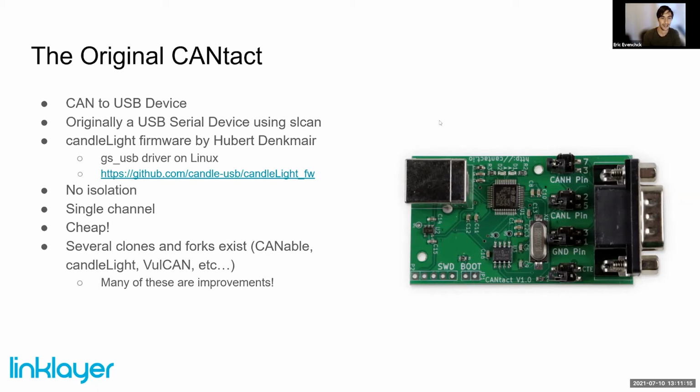So this device came out with the main support being SocketCAN on Linux. And because this microcontroller was cheap and had all the hardware, a few interesting things happened. Someone wrote a much improved firmware called Candlelight that talked to a driver that was built into the Linux kernel, and still is, meaning that out of the box, you can plug this in and you actually get a network device on Linux. And so that's quite useful in terms of being able to very quickly get up and running. There's no drivers to install in Linux.